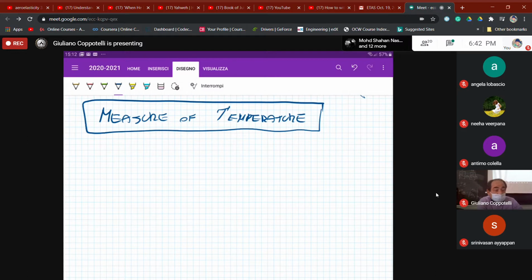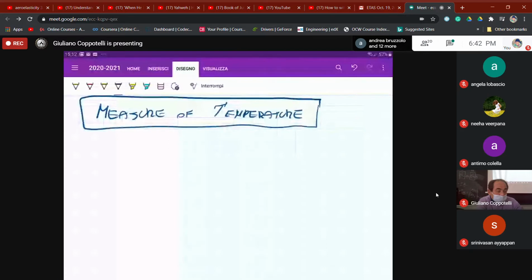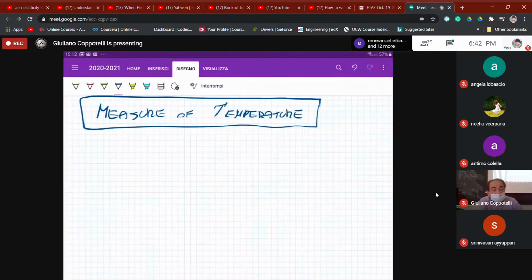The relation is linear for very small values of the strain. And because it is very small, in order to measure the strain, we have to use the Wheatstone bridge. We analyzed the Wheatstone bridge in terms of the measuring configuration: quarter, half, and full bridge configuration.